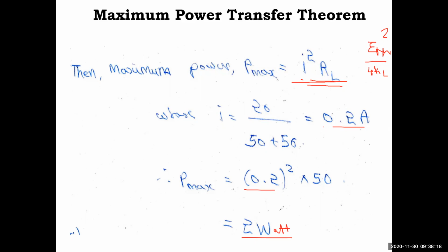So here Thevenin's theorem is required. Thevenin's theorem or Norton's equivalent gives the equivalent circuit. Then we equate that to RL, and then we'll find the I and the power. So this is the step. Now we'll consider a source side complex circuit, ZS, and we'll have the load as it is.